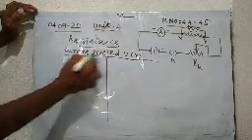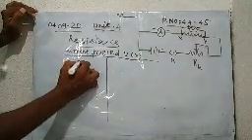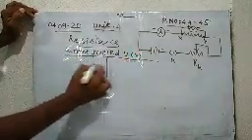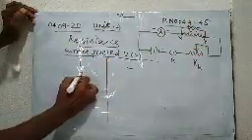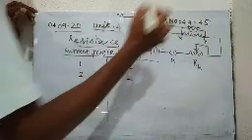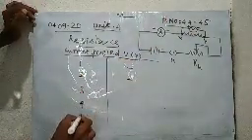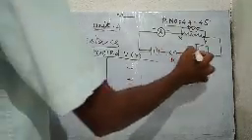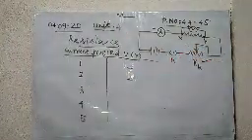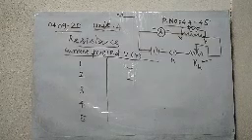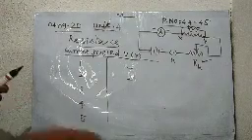By changing the current, first we pass 1 ampere current, then the potential difference is measured using the voltmeter. Then 2 ampere, and also 3 ampere, 4 ampere and 5 ampere. That means by varying the rheostat, the current through the conductor is varied and the corresponding potential difference is measured.